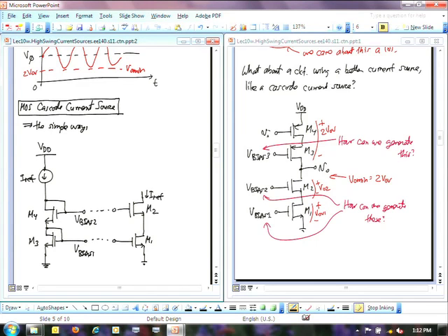Can you force it? Yeah, you can't, because you don't know what that voltage is. That voltage can be large enough to even create a channel there. You don't know if it's larger than VT at that point, right? It's going to be something. You might get lucky and be okay, but you don't want to take that chance.